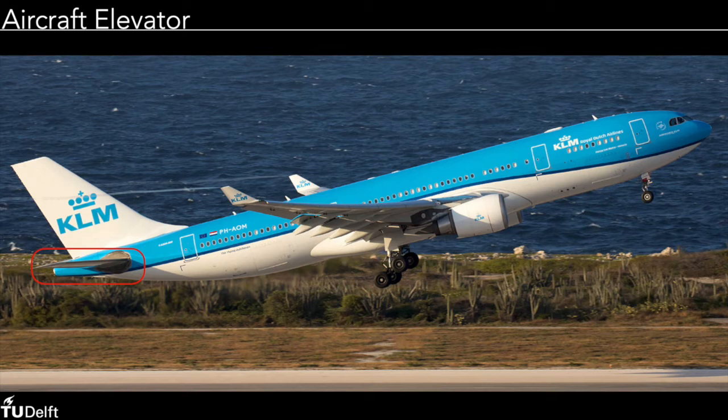These oscillatory faults, if they go undetected, can cause excessive loads on the control surfaces and the surrounding structures. These loads need to be considered in the structural design, thus adding additional weight to the aircraft, unless we can consistently detect and pacify these oscillatory faults. By guaranteeing fast detection of these faults, already at a low amplitude, much of the additional weight can be prevented with a purely software-based solution.